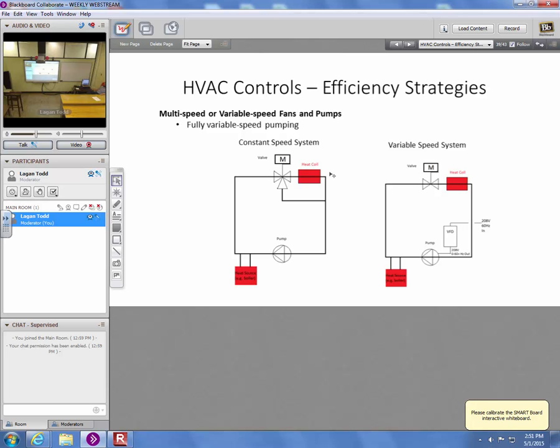Okay, so with the 3-way valve, you're circulating around, right? If you don't want heating at this heating coil, let's say it's baseboard radiation in the bedroom, you just open this port down here and send the water around it and back. If you do want heat in the bedroom, you open this port and send it through. If you want a little bit of heat, you send some through here and the rest through here. But either way, you're maintaining the same flow rate through the pump at all times, more or less. There'll be a little bit of change as this valve strokes, you see a little change in the pressure differential, and the flow rate changes a little bit.